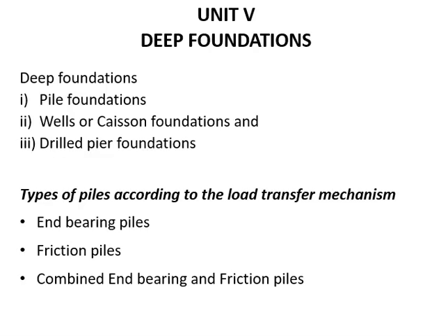Sometimes the term drilled pier is used for piles of a bigger diameter, of more than 1 meter, and they may go up to 5 meters or more. They are nothing but large diameter bored piles which may be belled at the bottom to give greater bearing area. The design principles of drilled piers are the same as those of piles. Piles are also used to take up uplift loads. Piles may be used as a single pile or in groups with vertical and batter piles.